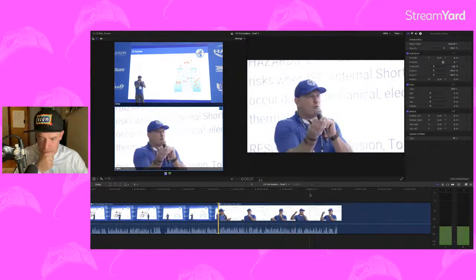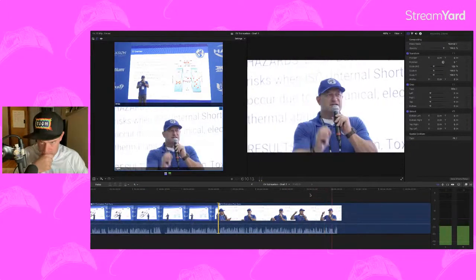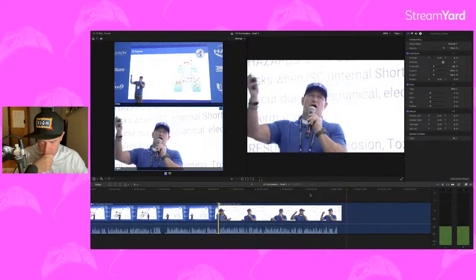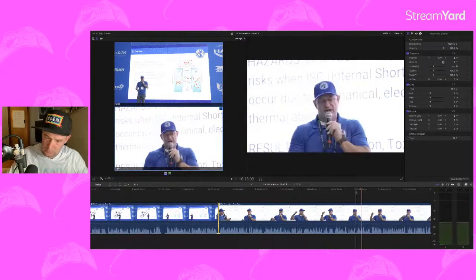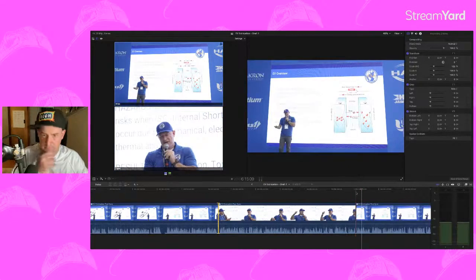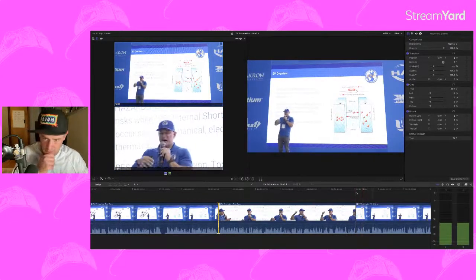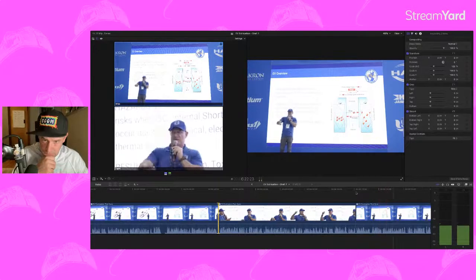Meaning one of them has certain chemistries, designs, and coatings that's designed to discharge lithium ions. The other one has components that are designed to charge lithium ions, okay? So I lay in this layer of noodles, and let's say it's an anode. My next layer would preferably be the cathode, which is the other side of that equation, so I can move these lithium ions back and forth.